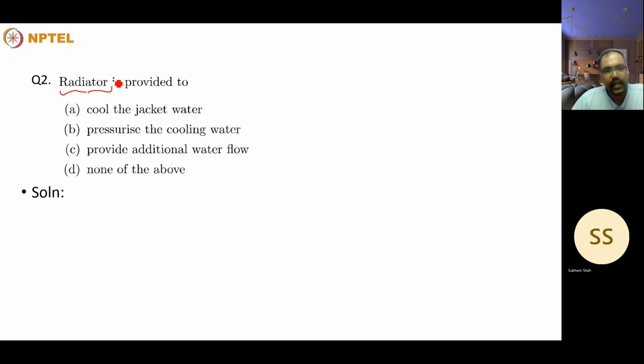So we have to somehow ensure that the heat absorbed by water should be released somehow. And that is being done by using this radiator setup where it acts by the principle of change in density. So the water which absorbs energy from the engine cylinder gets heated up, and the density of the water will be lighter, and that will be going upwards, while the cold water will be going downwards